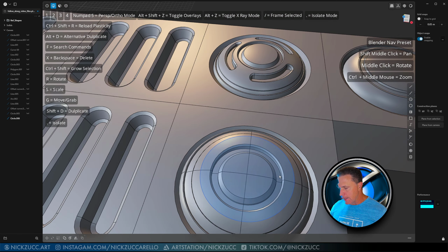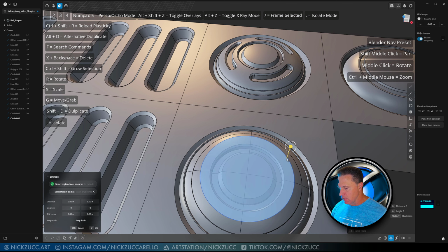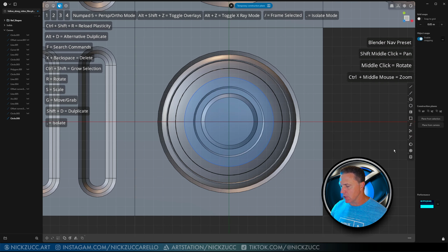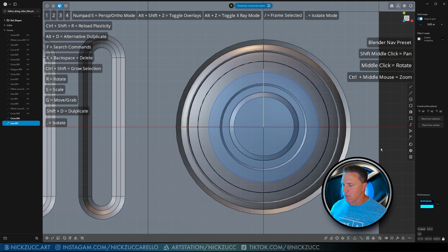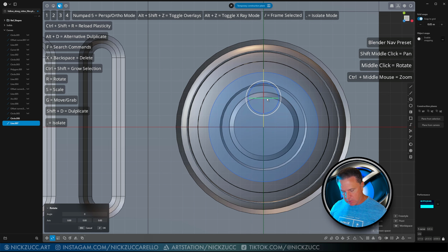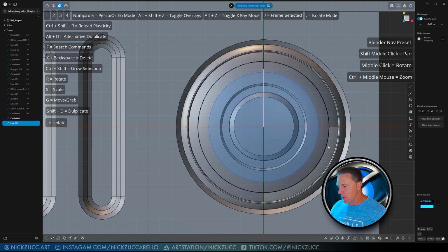Okay, so I can actually select this right here, and I can make a plane from selection and just go straight to the top like this. And if I wanted, I could click and drag out a curve. Let me snap to grid and turn these off. So I'm just snapping to the grid at this point, and I'm going to make a curve right there. I could rotate the thing and then tap V and put it right down here and then rotate like this and maybe do 15-degree increments. It's one thing I could do.